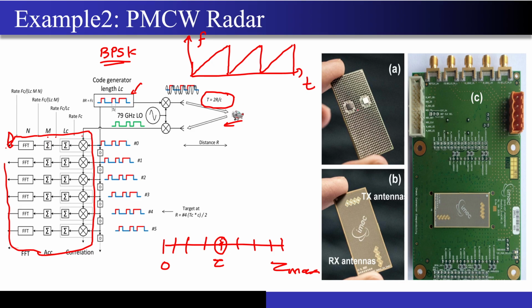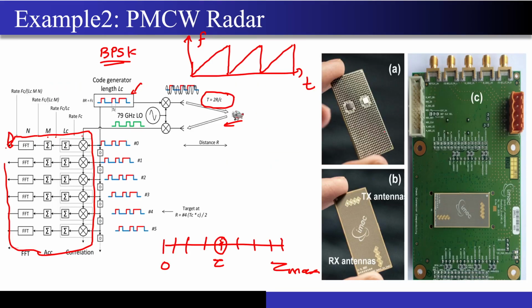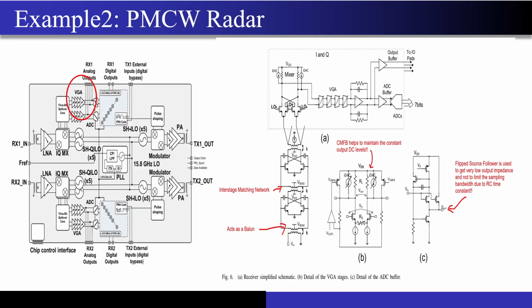Again, you are able to at least see the package over here, correct? Since this frequency is very high, close to 79 gigahertz, if you calculate the lambda by 2 value, you are able to fabricate the antennas within the package itself. The antenna size becomes so small, correct? Once you have that package, you build a PCB board around it, and you can see the SMA connectors that I have talked about, the transmission lines and all, everything is present over here, right?